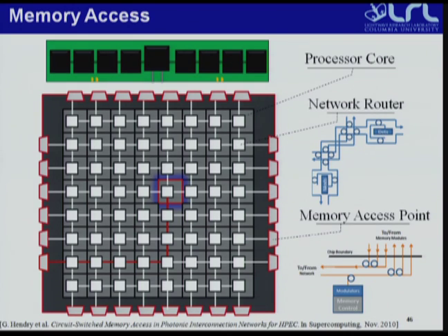And what we do is we bandwidth match what we can get on chip to parallel DRAM chips feeding into this optical circuit. And what we also get is that the memory controller logic is hugely simplified. All the memory controller has to worry about is row access and column access time. It doesn't have to worry about optimally scheduling all these small accesses into one DIMM to be able to get utilization out of it.